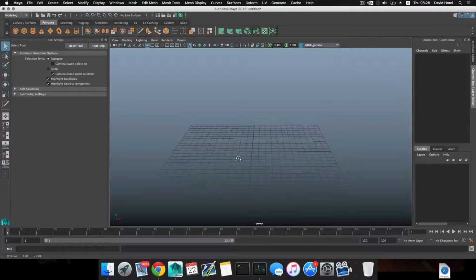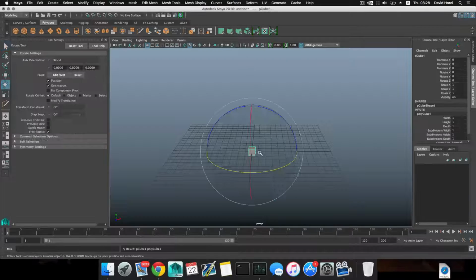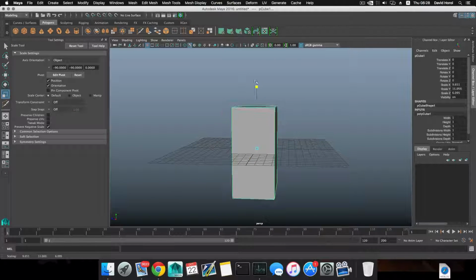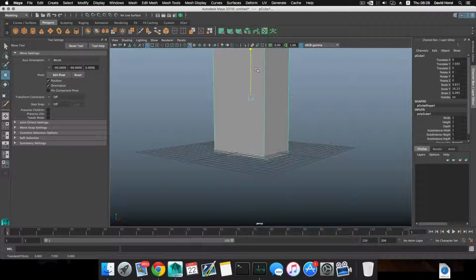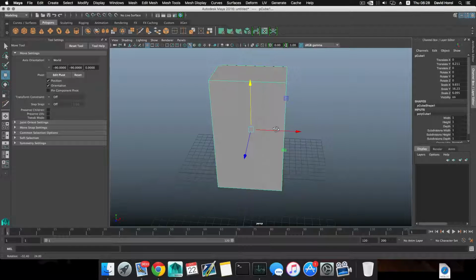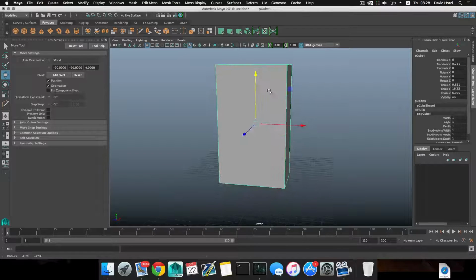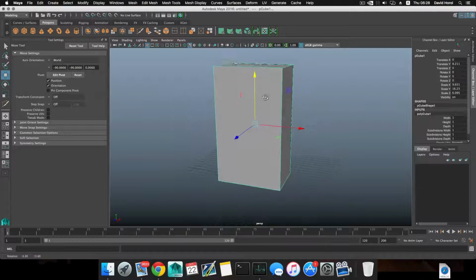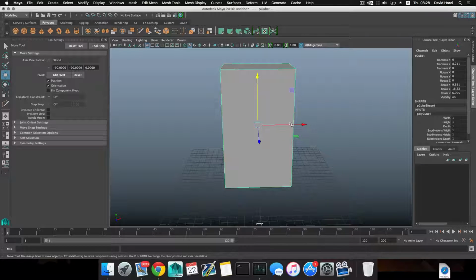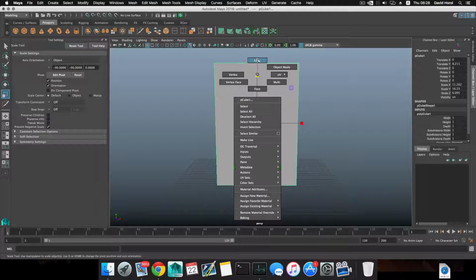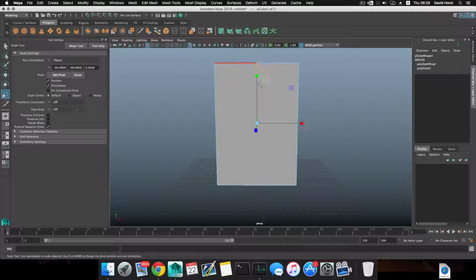Let's begin. We're going to block out first the entire figure, which is the main box. So I'm going to create a box like so, making it high enough. It's a heavy one, and the purpose is to hide as much as we can from that wall there, and just put something that will logically fit this area. So I'm going to expand this just a little bit like so. I'm going to right click, choose edge. Let's grab this edge, edge ring utilities, to edge ring and split.